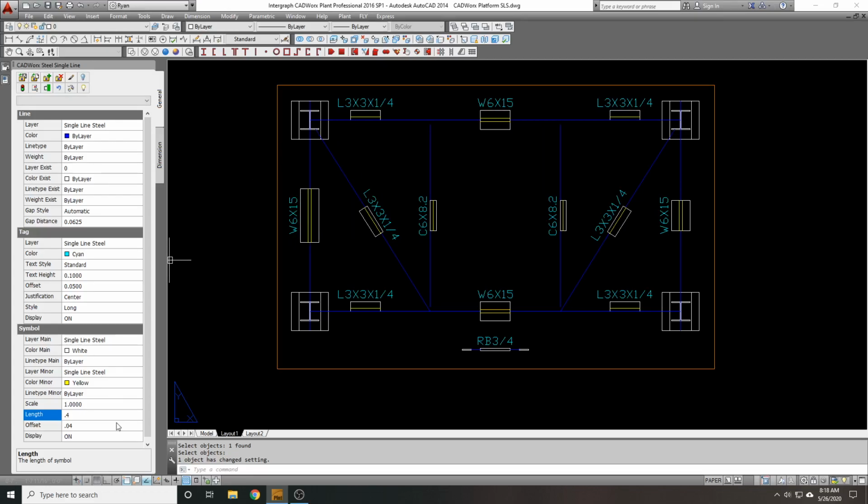You'll also notice that now I no longer have the name of my setting in here. That's because we've deviated from that setting. If I click this and hit plan, it changes me back to my default values. Well, let's say I don't, I hit apply settings and it goes back and changes everything back to the way it was, except for this one that had the manual override. How do I get this one to go back to the way it was? That's where you can say reset settings, and you can reset that one member and it resets it back to the default that it was when you generated.